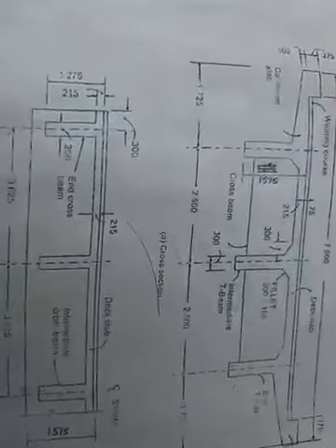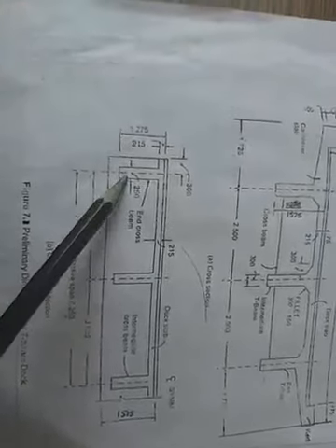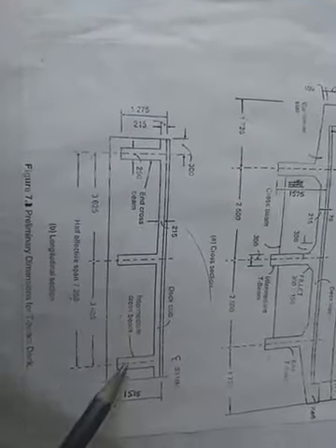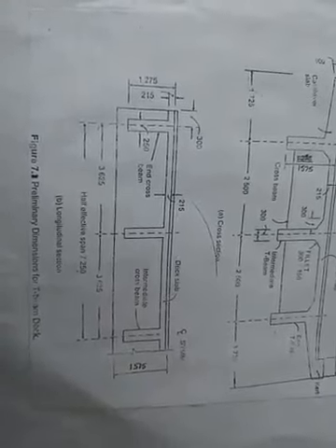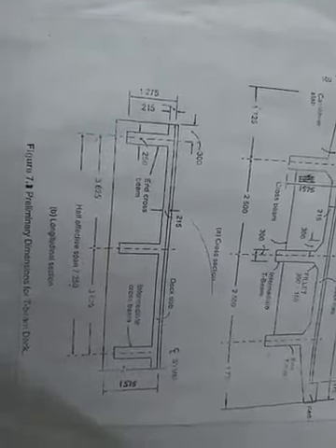You can see over here the cross beams. Now the major concern is with the longitudinal section. The cross beams are placed at 3.625 meters. These are the end cross beams. All others are the intermediate cross beams, and at the end you have again an end cross beam. So we have 5 cross beams. 3 are the intermediate, and at the ends the 2 are the end cross beams.